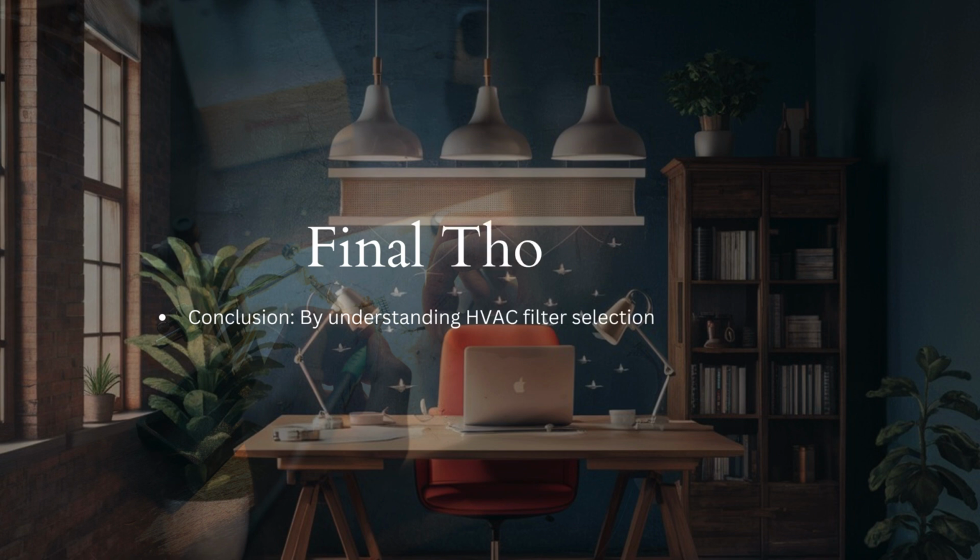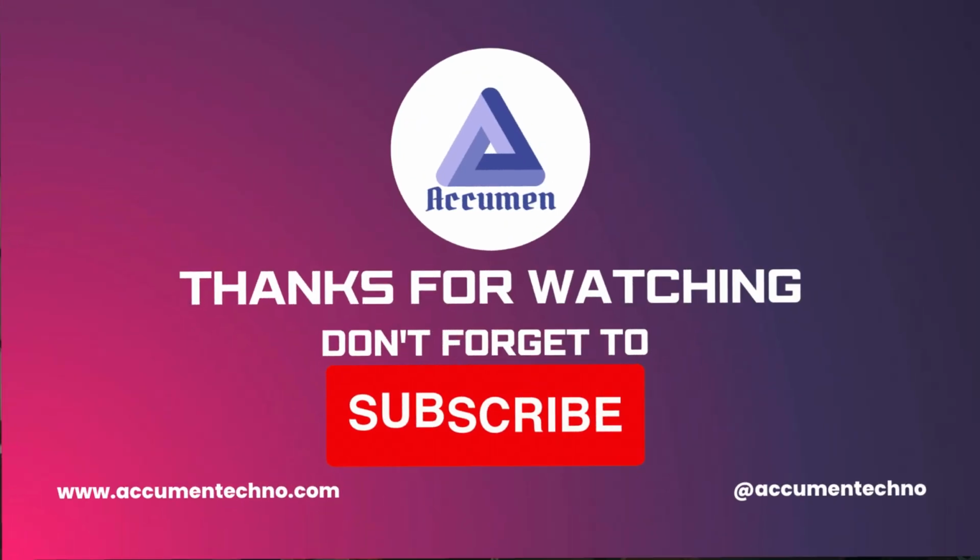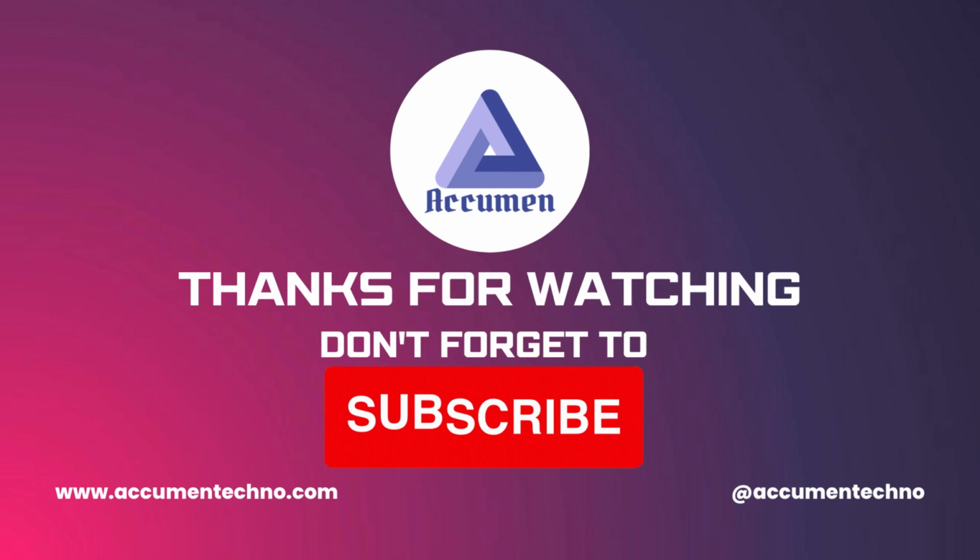In summary, the new ASHRAE Standard 52.2 provides more control over tailoring the quality of the facility's air supply. MERV ratings encourage filter selection based on particle size requirements, and the evolution of air filtration standards has led to more precise and accurate testing procedures. By understanding HVAC filter selection and MERV ratings, facility managers can create a healthier and more productive indoor work environment.